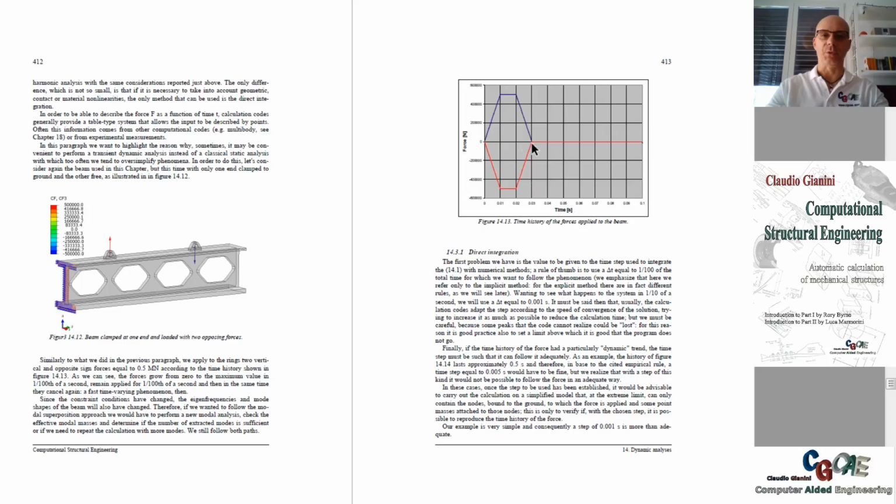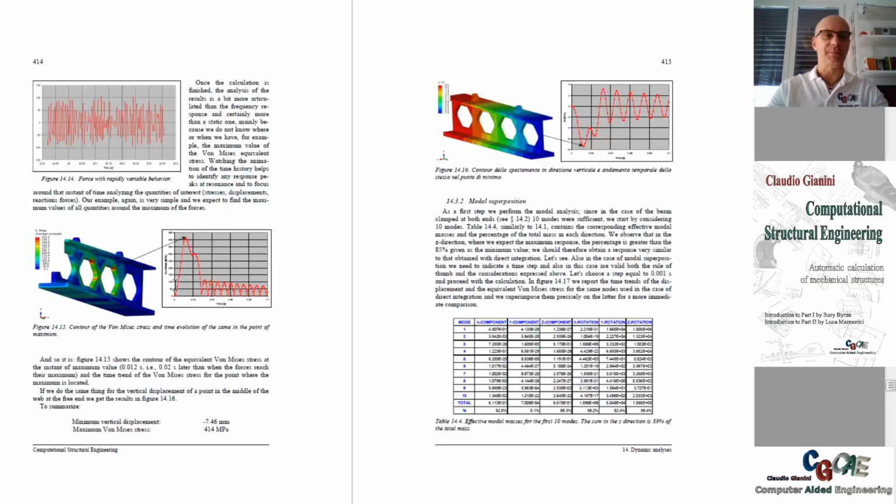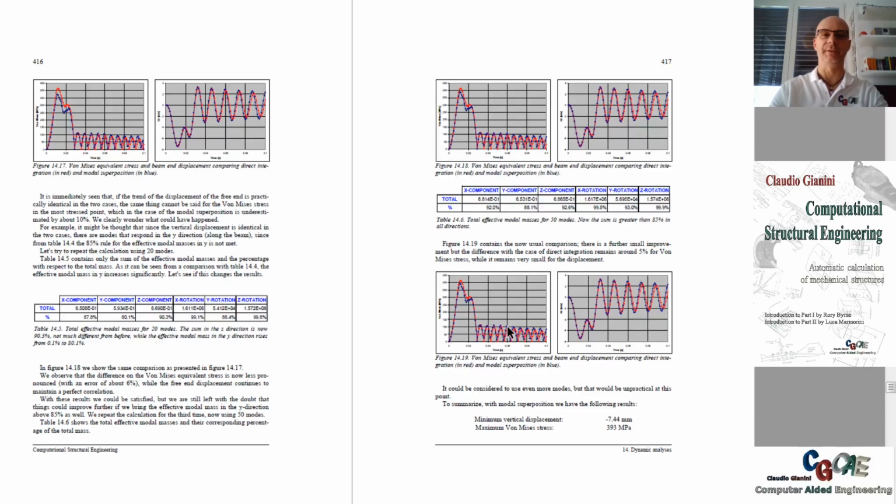Okay, then we switch to this one. We solve the problem. Then we look for the maximum stress and the displacement. So what is the time history of the response? And with the direct integration, then we switch to the modal superposition. We look at the effective modal masses to see if we think we have enough.